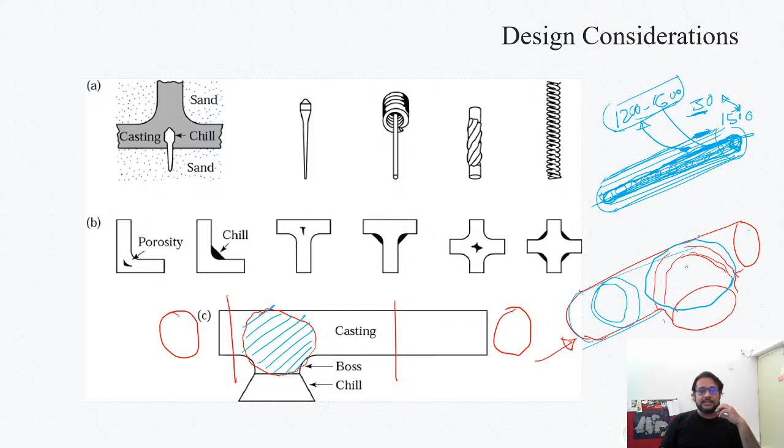However, in something like this, you will have the same kind of action going on, but imagine this area. You would have this large ball where the temperature difference between this surface and just the area outside it is not too high. As it cools down, this part has already solidified, so that means it can't move, and this part is solidifying, so it is shrinking.